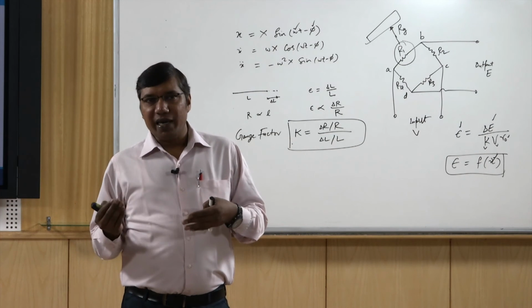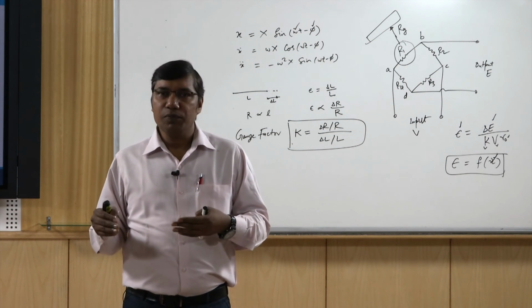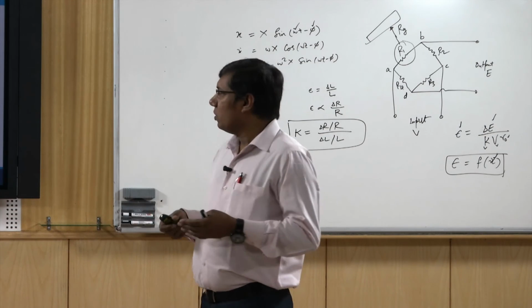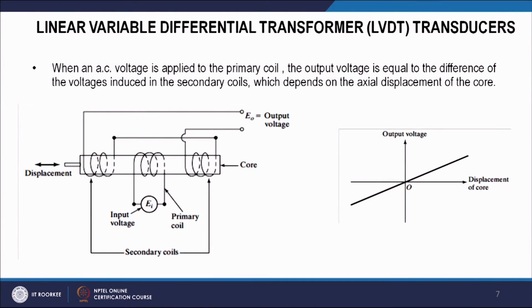If it is in the opposite direction, it enters more into the other coil. So it also measures the direction, and so measures the vibration with respect to the equilibrium point. Here is the linear voltage displacement response of this system for a small movement of the core. We can see zero here, and it is linear on both sides, the positive and negative displacement side.